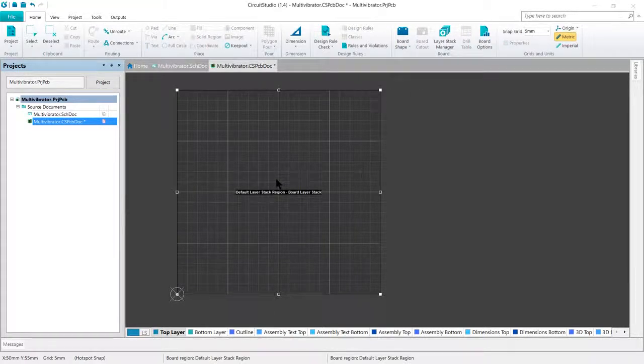The objective is to resize the shape to create a 30mm by 30mm board. The coarse visible grid is 25mm, essentially 5 times the snap grid, and the fine visible grid is 5mm, and this will be used as a guide. So you can now either slide the upper and right edges down and in to create the correct size, or move the 3 corners in, leaving the one side that is at the origin in its current location.